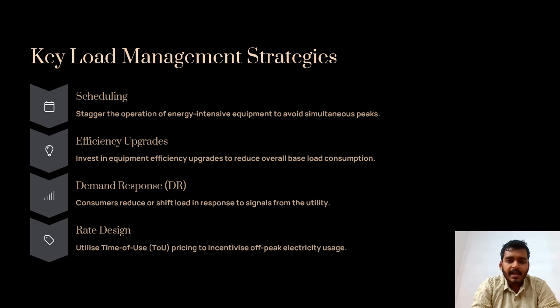Key load management strategies. Scheduling: schedule the operation of energy intensive equipment to avoid simultaneous peak loads. Efficiency upgrades: invest in equipment efficiency upgrades to reduce overall base load consumption. Demand response: consumers reduce demand by shifting load in response to signals from the utility. Rate design: time of use rates encourage electricity usage away from peak load.